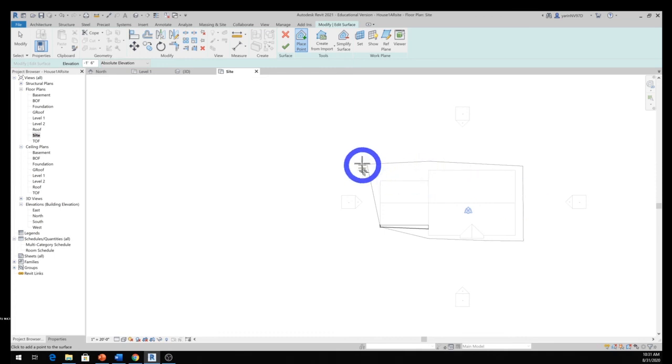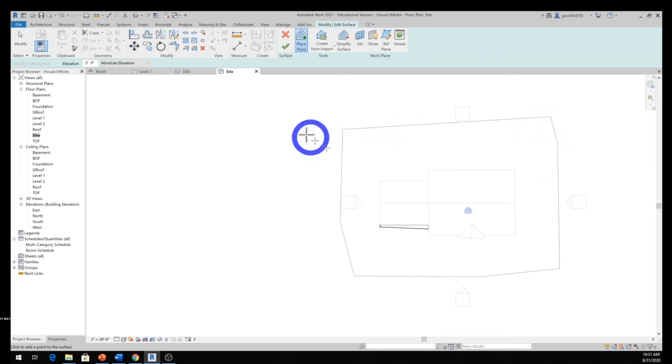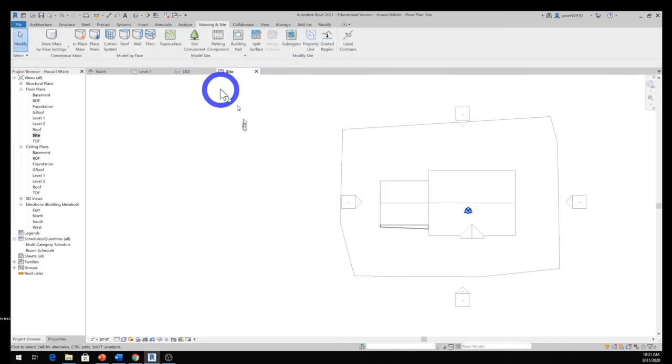and rainwater from the roof can drain away. And now we can change our elevation even further, maybe minus 3 feet or minus 2 feet 6 inches. You can drop every foot or every foot and a half. It depends on your ground topography or your design. So I'm going to go with minus 3, and I'm going to make it like this. And that's not a bad slope for a yard. Let's click the check mark and take a look at the 3D view.